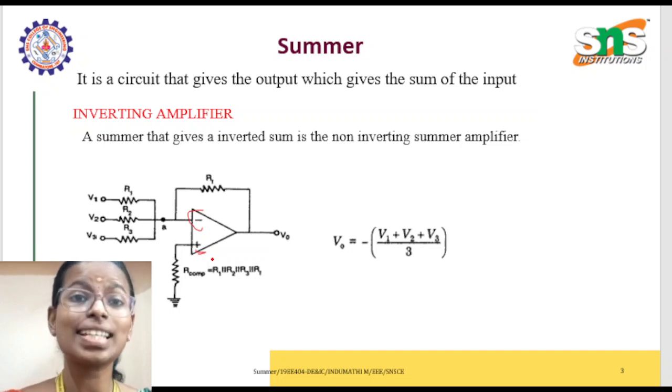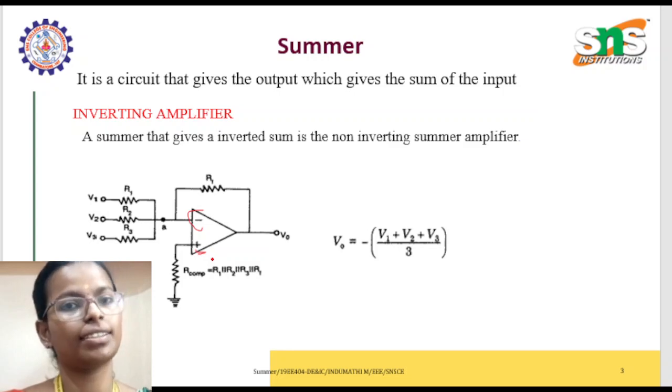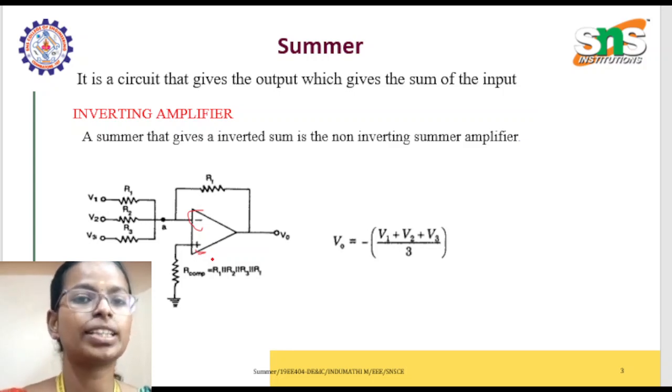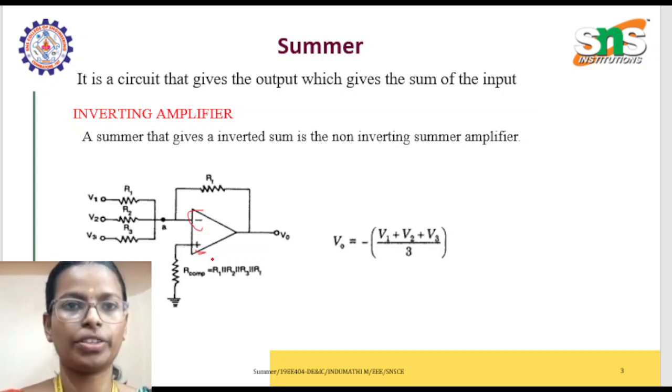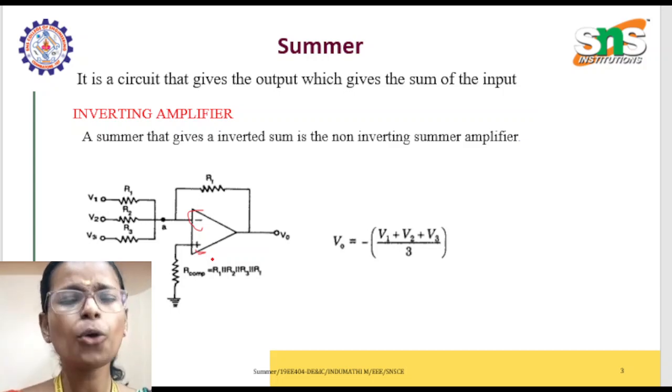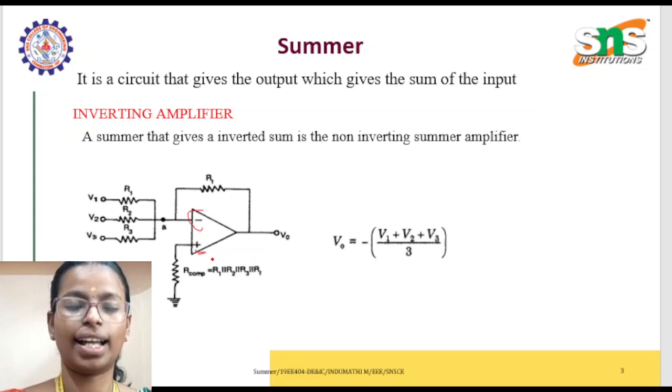So this is the circuit diagram. The input is on the inverting terminal and the output is at V0. When you give a sinusoidal input, you'll get an inverted output with amplification. There are two processes happening here: one is amplifying, and the other is inverting.